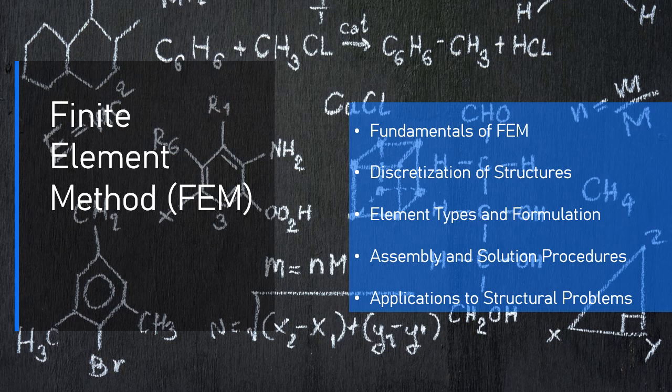3D elements, solid elements, used for modeling bulk structures or objects that experience 3D deformations. Common types: hexahedral, brick elements, tetrahedral elements, pyramid elements. These elements are used to capture the behavior of volumetric structures where all three dimensions of the material contribute to the deformation.